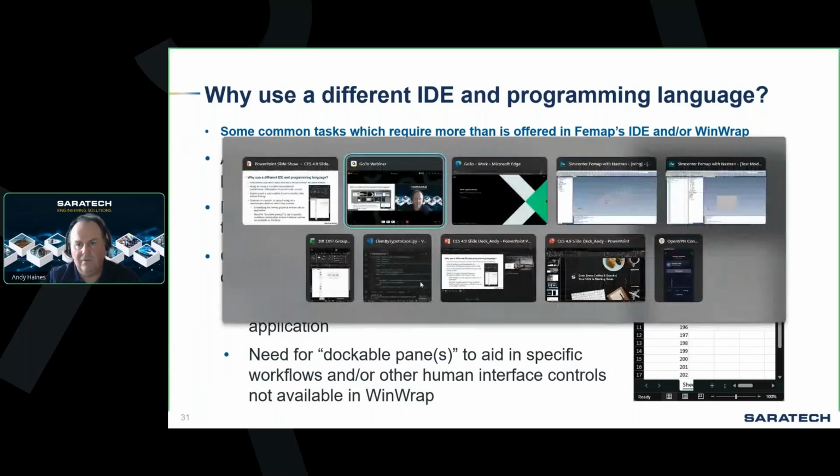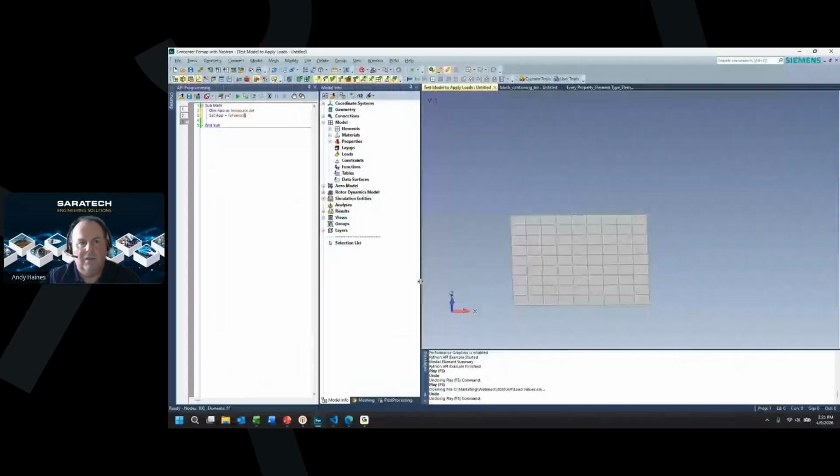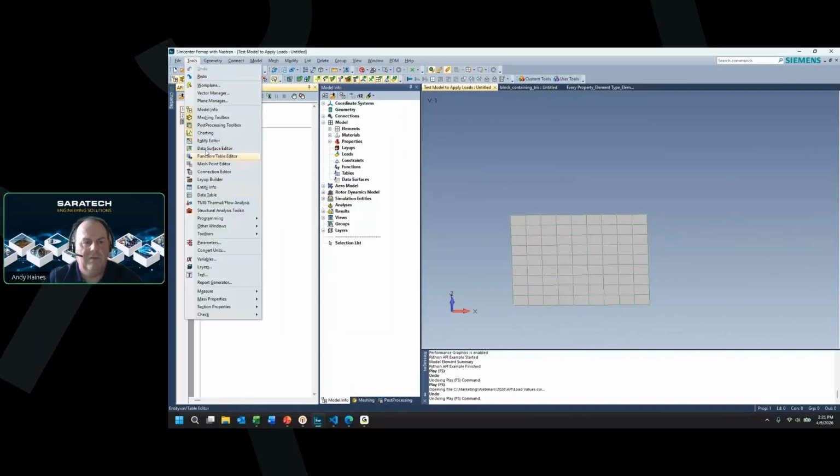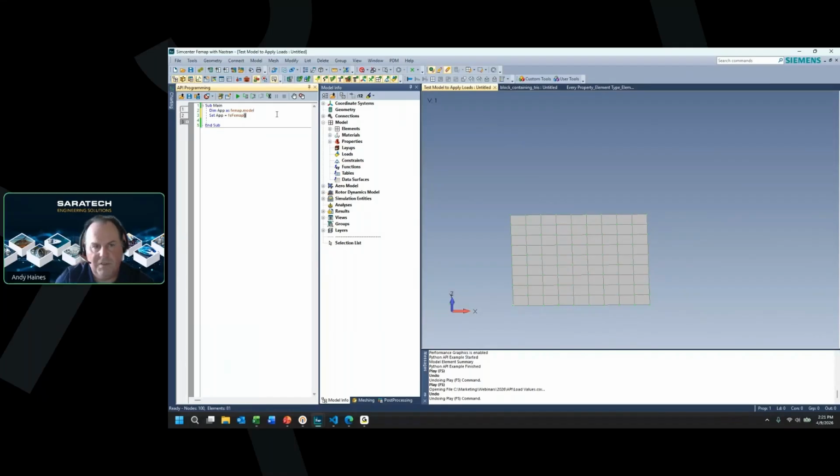So here, let's just go over to Femap, and we'll start here. All right, so again, I already have the API programming window open, but if I didn't, I could just come here to go to Tools, Programming API. The first thing we're going to do is dim something like ND as Femap dot, and then these are all of our different objects that are available. So I'm just going to say node, and then I'm just going to set ND equal to app.feNode.